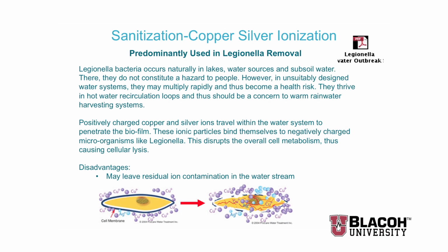Kind of as a side case here, Legionella, as I mentioned in that one example before, when we were talking about what could be in your water, Legionella is not found in rainwater systems, generally speaking, because Legionella is found only in standing bodies of water and only propagates at very specific conditions, which are typically about 90 to 95 degrees Fahrenheit, or that's why you see them a lot in hot water loops, for example, in hospitals, places like that.